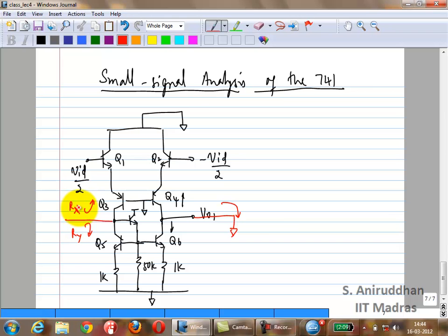Okay, so what do you think it is going to be? What was here before we added this transistor? There was a short. What is the impedance when there was a short? 1 by GM. Right? After adding this transistor, what has changed in the signal sense? Okay, no, R pi. What is the fundamental reason you got 1 over GM there? Because you are basically taking your collector signal and feeding it back to the base. Right? That's why you got the 1 over GM.